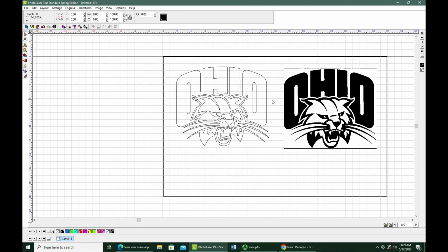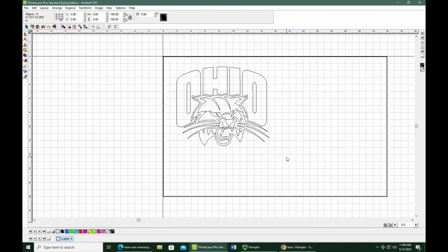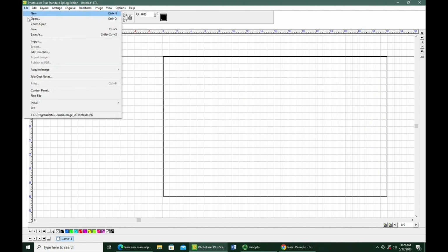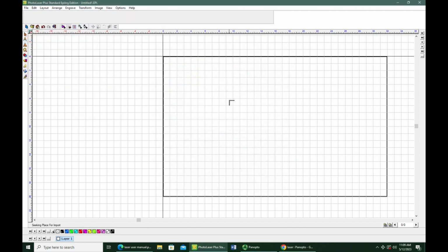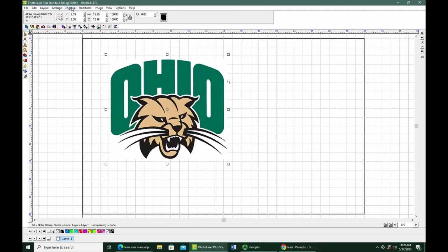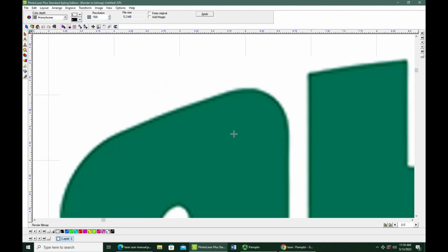There are multiple ways. The other day when I was practicing, I did 3 or 4 different ways, and I've forgotten one of them where I removed it away. One thing you can do, which doesn't always work, if I bring in the image again, if you just convert this directly to a bitmap and you do the monochromatic, what it will do is take all of these lines right here and it just blocks them all off, and sometimes that leads to a very poor vectorization. So you can't always use this tool. It only works in this case because it's very clean.